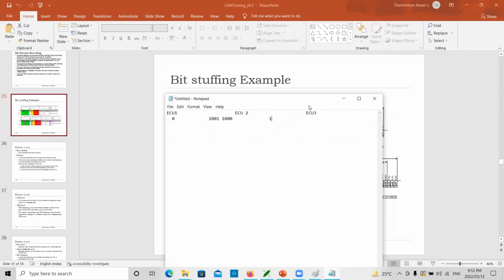So ECU3 will lose the bus at the last bit. In the 11th comparison cycle, he will lose the bus. That is the last bit, the last round that he has to win. See, he still had hope through 10 bits of shifting. He had hopes to win, but at the end, he lost the bus.